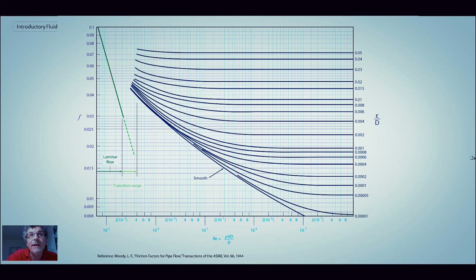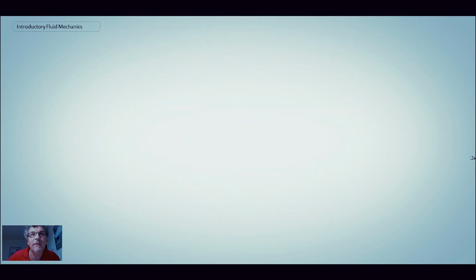And so that is the Moody diagram. That's a diagram that we use quite extensively within mechanical engineering in order to give us the friction factor and estimating the pressure drop within pipe flow. Or you could estimate other things. You could be doing sizing and determining the diameter, or you could be determining the volumetric flow rate going through a given pipe flow configuration.